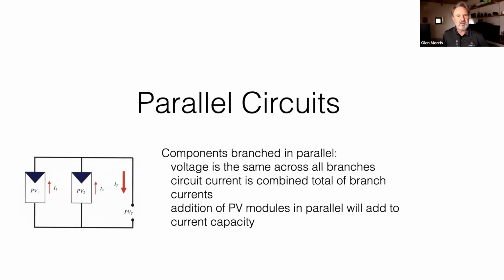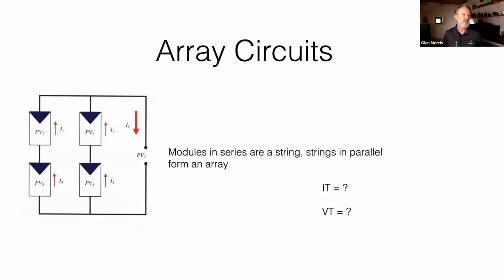And so, two or three panels in series was about the maximum you could put often on many of the DC coupled off-grid systems. And so we would see a lot of paralleling in a larger off-grid direct DC charging to a battery system. You can actually combine both of these, by the way. So here we've got parallel and series in one system. So we now got an array of 4 panels, and we've got 2 strings. A string is a series connection of modules, and 2 strings are in parallel.